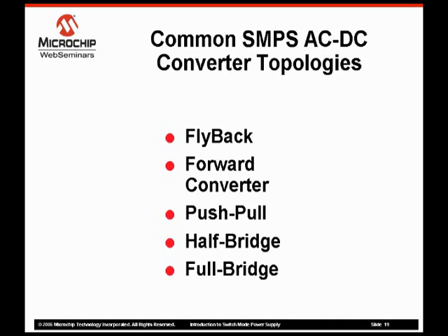Flyback converters are low-cost designs typically used for low-power applications of 5 to 150 watts. Flyback converters also do not require output inductors, which saves cost. The forward converter can be designed with 1 or 2 transistors and is typically used for 100 to 200 watt applications. The push-pull converter has moderate complexity using 2 transistors and is used for medium power applications of 150 to 300 watts. This topology subjects the transistors to high voltage stresses and is not often used for modern offline applications.